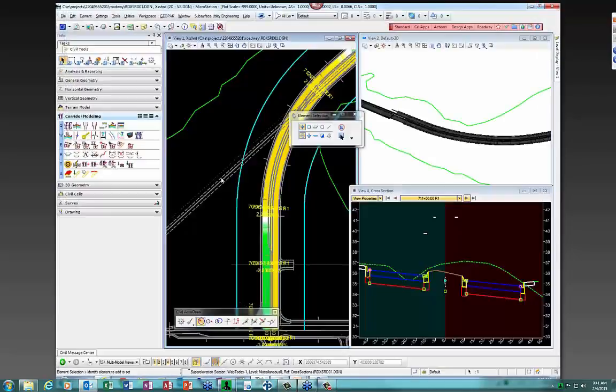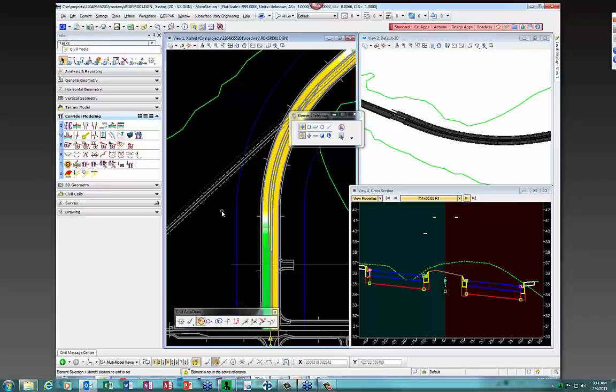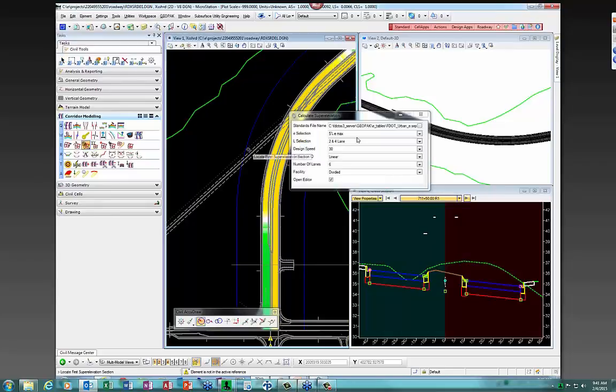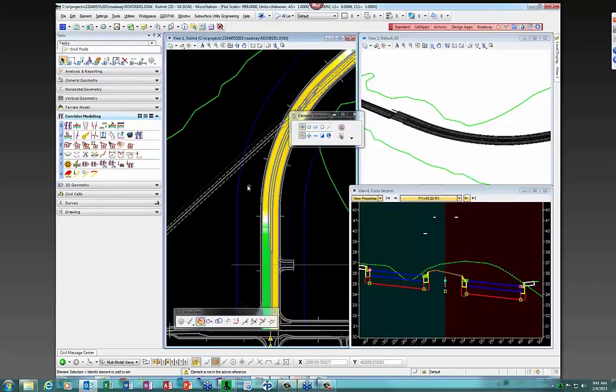The reason I show you that is because if you wanted to, instead of calculate superelevation using the e-tables, once you have a superelevation set, what I could also do is come out here and go to my F11, actually go to my editor and select this. I don't know if the editor will open up and then activate, so I may have to just change.